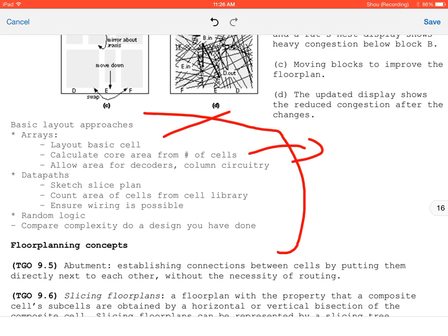So now you have to have a 5 to 32 decoder. That's why our 5 bits from our instruction are coming in. You have to decode that to 32 because that 32-bit output becomes a word line to determine whether or not we need to read from or write to it, correct? So you need these decoders and column circuitry to make sure that you're properly driving the interconnect parasitic capacitance, so you're meeting proper timing constraints. Then you have to worry about interconnects to make sure you're properly driving those wires, especially with memory.